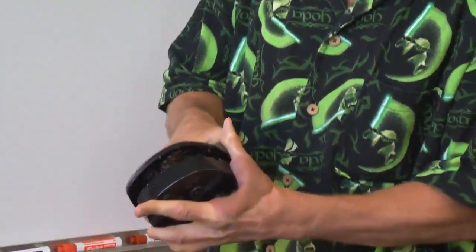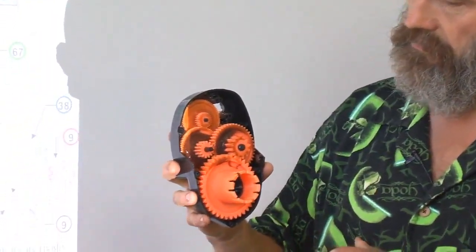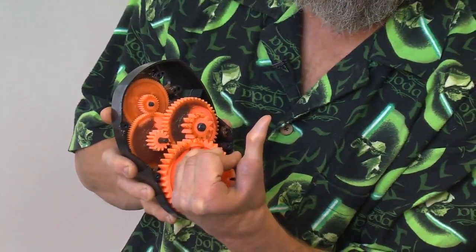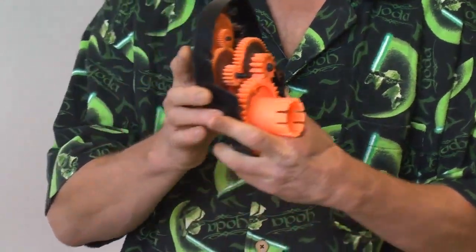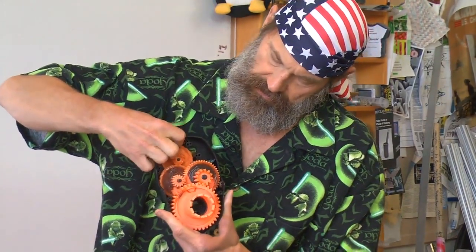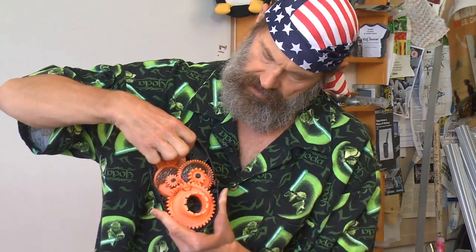Let's see what kind of a gear train we have in here. I've taken the screws out already, so the top cover comes off. You can see the grease here. And watch what happens when I turn this input. The output moves really fast. Is that really what would happen? Or more realistically, is there actually a small motor that goes in here, a very high-speed, low-torque pinion, that would turn this large gear, and as the large gear turns, the output gear here barely moves. This is actually how it really works.